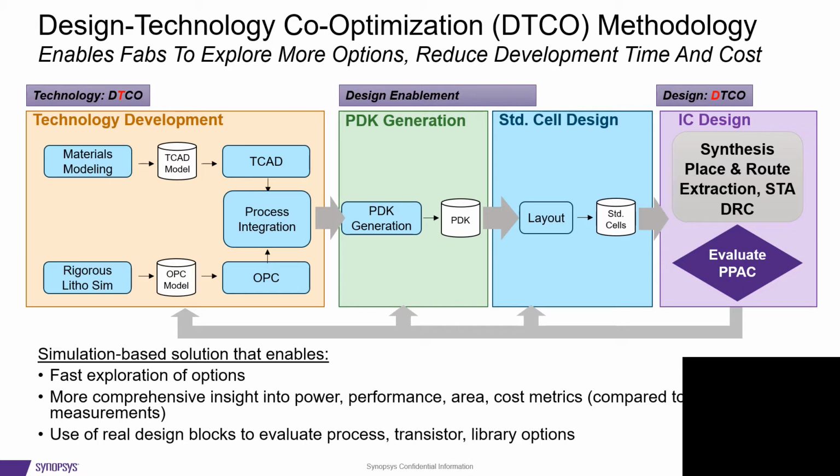So in this slide, we give you a presentation of the technology development itself. We have TCAD tools and we have design enhancement tools or layout enhancement tools. For the TCAD tools, we do physics-based mathematical analysis of the Josephson junction for modeling, starting with the materials and layout, and we integrate that with OPC procedures for making sure the layout reflects all the additional changes made for manufacturability.